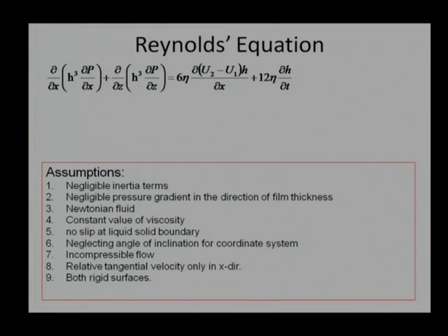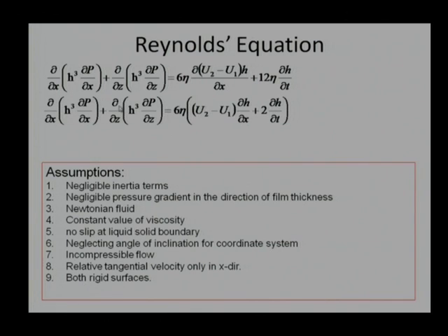We are talking about metals or ceramics which cannot be stretched so easily. However, even if it is stretched, the stretching action is negligible for our calculation. So, with the assumption of both rigid surfaces, the variation of relative velocity with respect to x can be neglected.